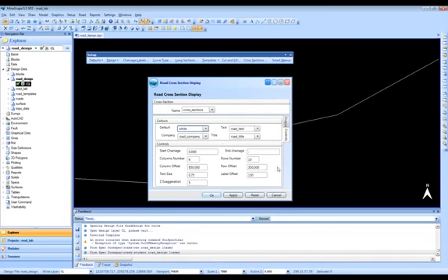And then down here, you're really setting up some controls on how to lay out these cross sections. Basically, these cross sections are going to be laid out in a row-column fashion. So you can specify how many columns you want, how many rows you want, and it's just going to start generating these things. And you can put some offsets, both up and down and across, for how that's going to happen. Some text size, Z exaggeration, how you want that Z exaggeration to look, etc. So these are all user definable. You set that up the way you like it, and then just say OK.